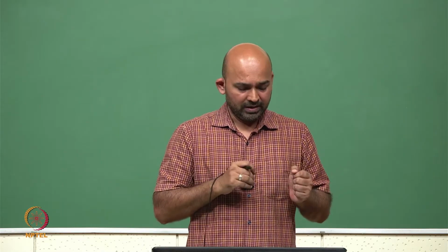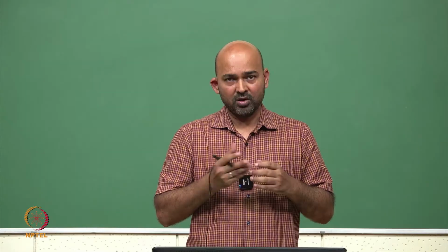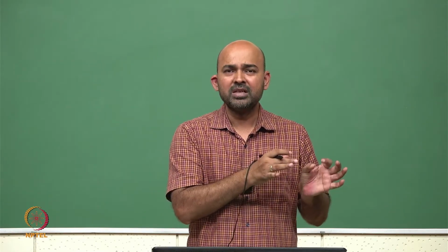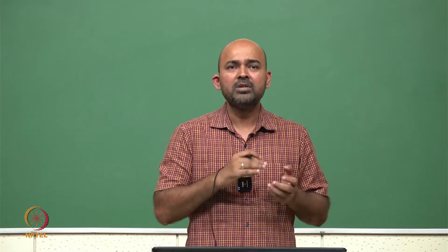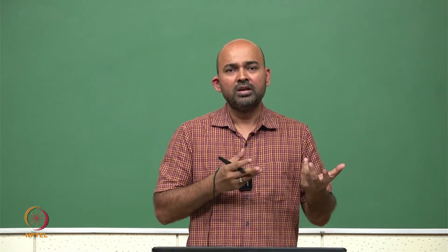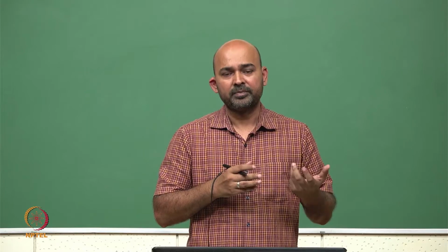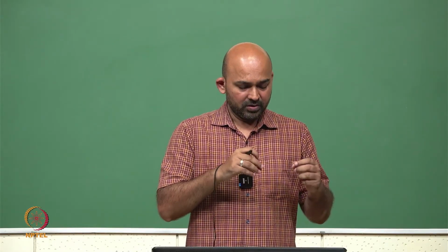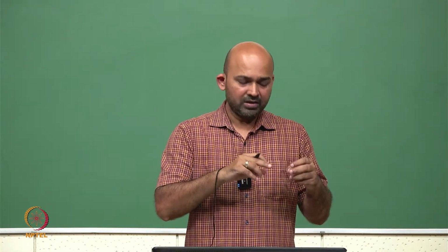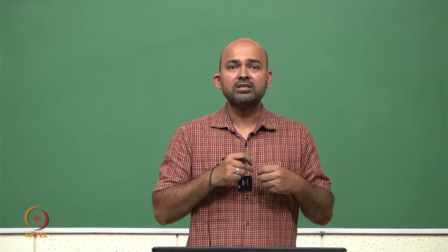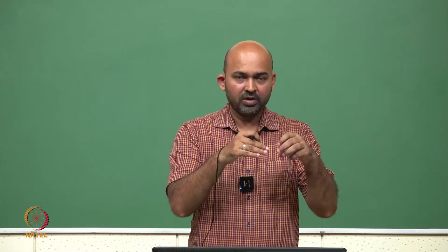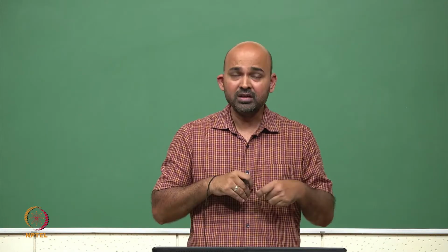For example, input 1 is a clock and the other inputs, input 2 and input 3, are very stable kind of data which sometimes comes in from slow electronics, or electronics which is not functioning very fast. So in that case, if we rearrange these MOSFETs in such a way that input 1 is applied to MOSFET 3 and input 3 is applied to MOSFET 1.